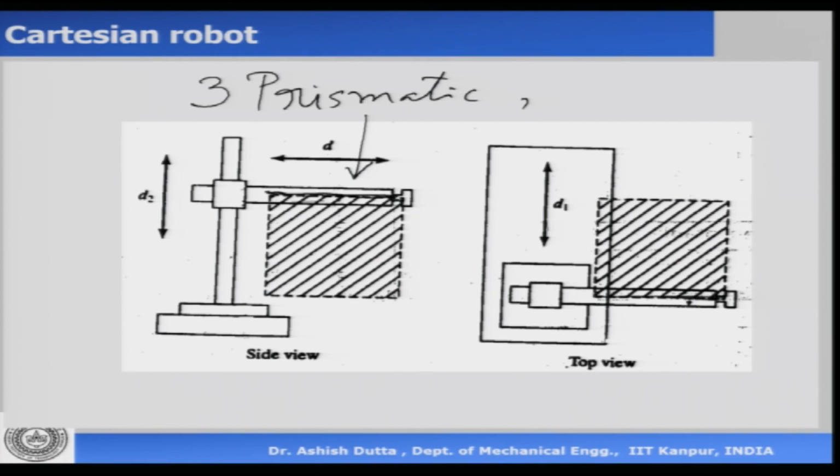So, this is my line which is seen. Now, when this joint moves, it moves from here to there in a straight line. So, what would happen is, this straight line is getting pulled along this direction and it comes till here. So, this is the full area that the straight line sweeps, and it comes out like this. So, in the top view, what we have is a square or a rectangle. In the front view, in the side view, again we have a square or a rectangle which is like this.